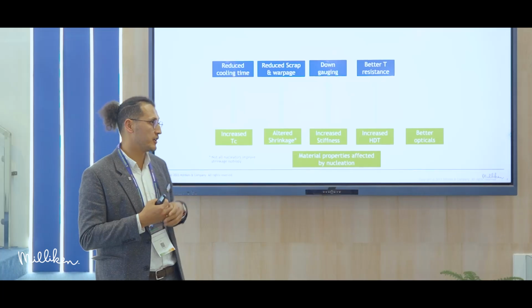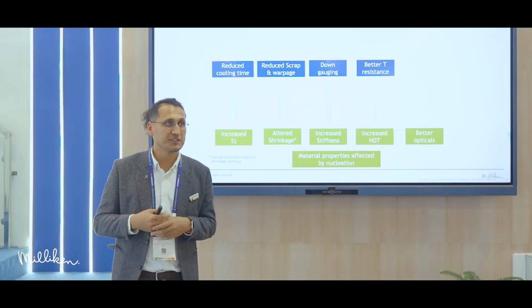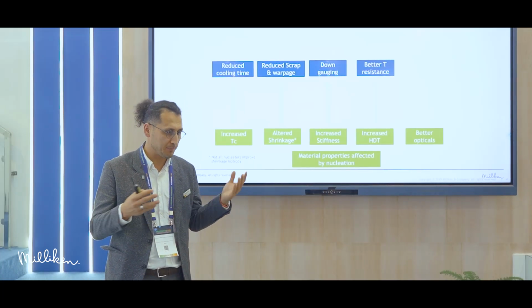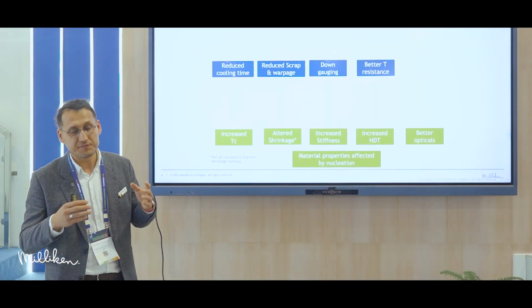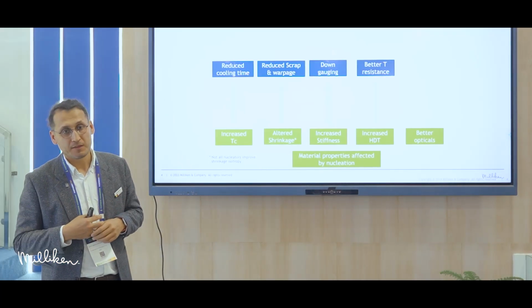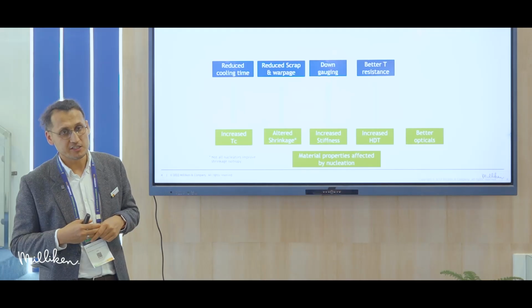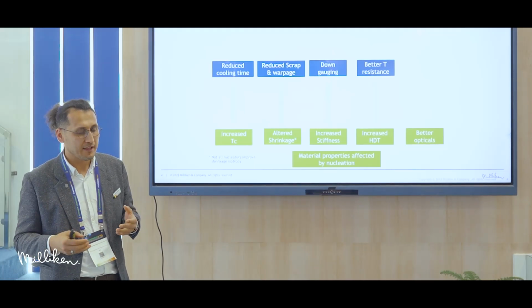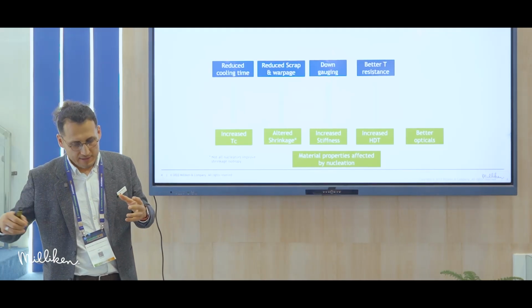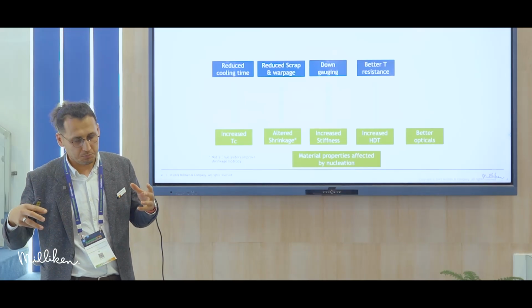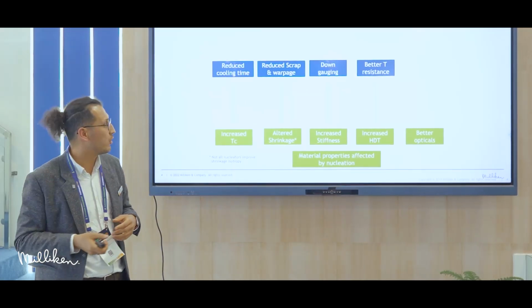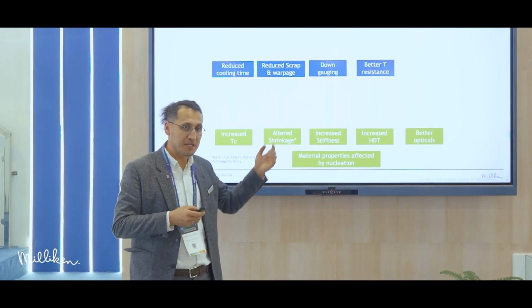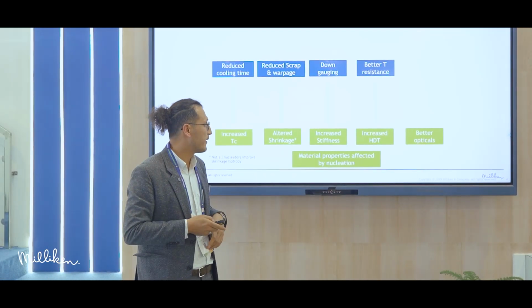At my last Japan expo, I saw a Japanese customer using a PP with a 150 Celsius HDT value for food packaging, and they want a fast steam process in the convenience store chain. So HDT can be improved by a nucleator as well.